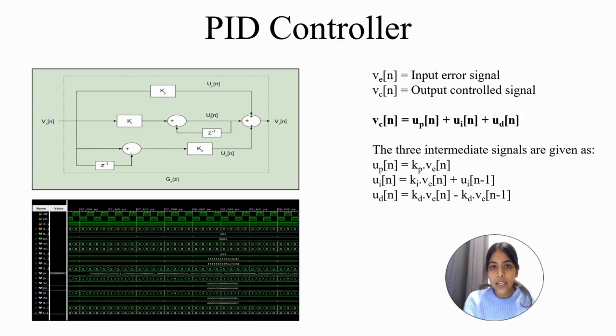The proportional gain determines the immediate response to any error, whereas the integral gain eliminates the steady state error by accumulating past errors, and the derivative gain anticipates future error based on the rate of change to achieve excellent stability and performance. Properly tuned discrete PID controllers are used for our UAV. They require less memory and processing power compared to continuous implementations. These are the simulation results for our Verilog design for PID.